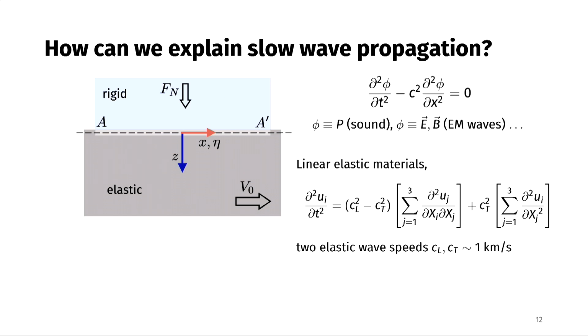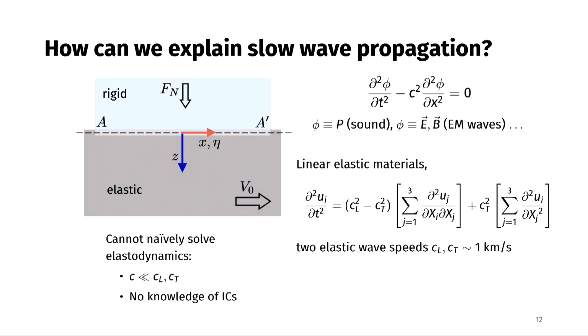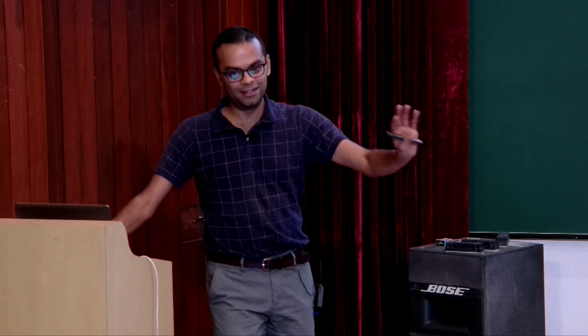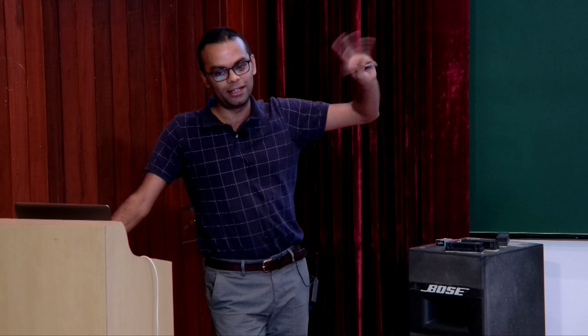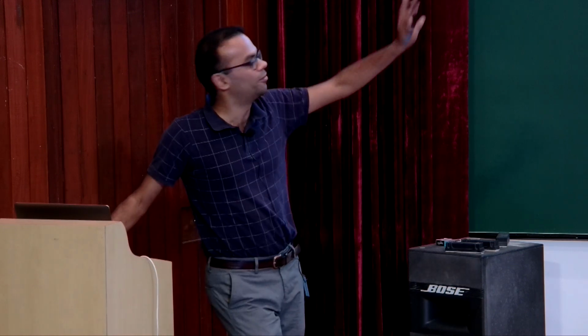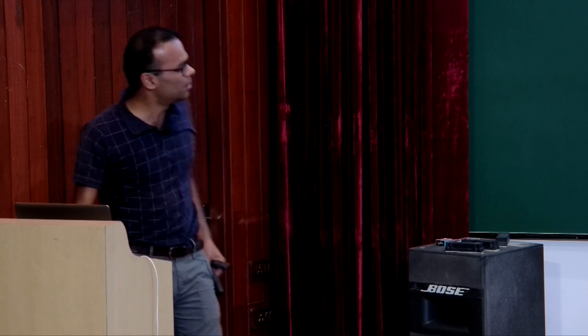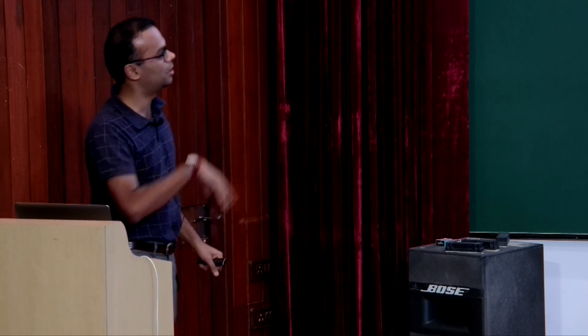And they're both for this material of the order of 1,000 meters per second, right? But our waves go at about 100 millimeters per second. So it's several orders of magnitude slower. This is a rubber, yes. There is also a viscoelastic timescale effect. They are lower, yes. So this one is hardened, so the cross-linking density is higher. So it's about 800-ish meters per second. So it's order of magnitude, right? But typically, if you have a very flexible rubber, you're looking at a couple of 100 meters per second.